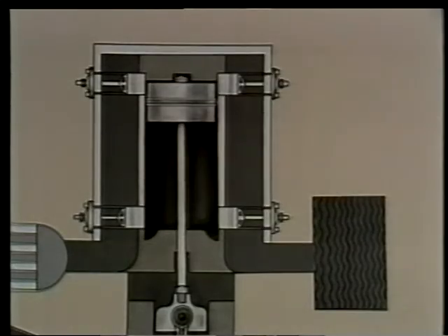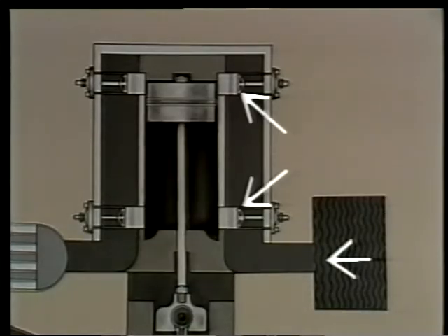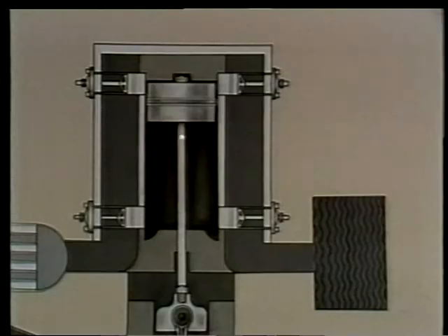Before air enters the compressor, it passes through an intake air filter. The filter keeps the abrasive dust and other impurities from damaging the piston and cylinders. Air then flows into the first stage cylinder through its 2 inlet valves. On an upstroke, air enters through the lower inlet valve and exits through the upper discharge valve. On a downstroke, air enters the upper inlet valve and leaves through the lower discharge valve.